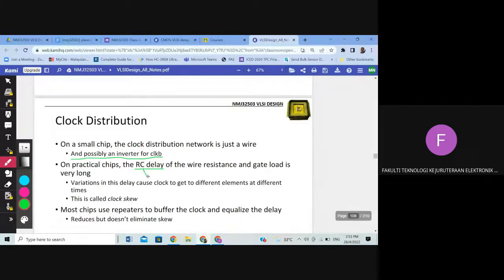And C is not a capacitor that we create in the chip. It is a capacitance that exists due to the wiring in the chip. For example, we have two wires here with a gap in between, an air gap or insulator. This unintentionally creates a capacitor, because two conducting wires with a gap between them introduce capacitance.